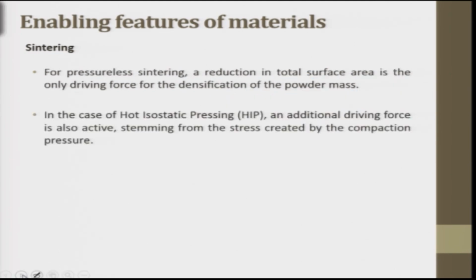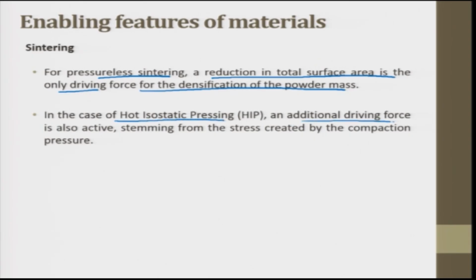Pressureless sintering is also one of the ways. For pressureless sintering, a reduction in total surface area is the only driving force for the densification of the powder mass. In the case of HIP, hot isostatic pressing, an additional driving force is also active, stemming from the stress created by the compaction pressure.